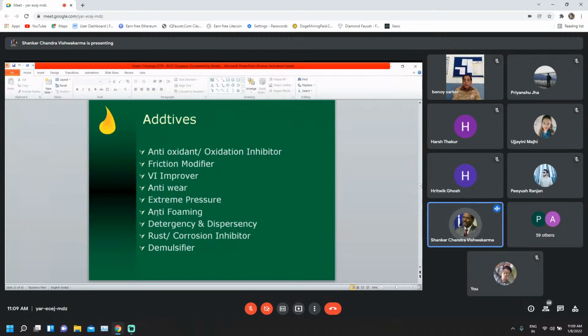The oils or lubricants are also required to have anti-foaming additives. This is important when there is a lot of heat. Not only the heat ingress, the contaminants such as water or air are trapped into the lubrication circuit. So in those circuits, the foam will start forming, and the oil should have the capability to reduce the foaming ability. That additive is called an anti-foaming additive.